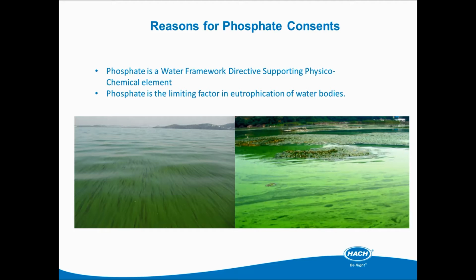Other drawbacks are the clogging of normal river flows, slowing the velocity and hence risking summertime flooding in storms, and the production of algal blooms which can block intake filters of drinking water plants. Some conditions promote blue-green algal blooms which can produce toxic compounds, making the water unsuitable for use as drinking water or killing other organisms. When these blooms form, the thick mats of algae on the surface can prevent sunlight from reaching lower down the water column.